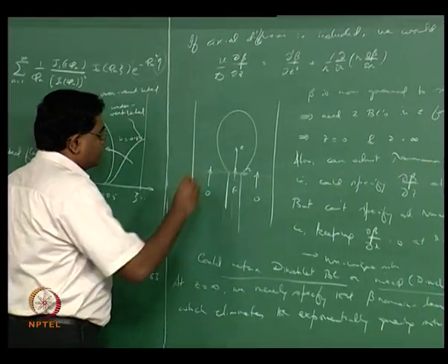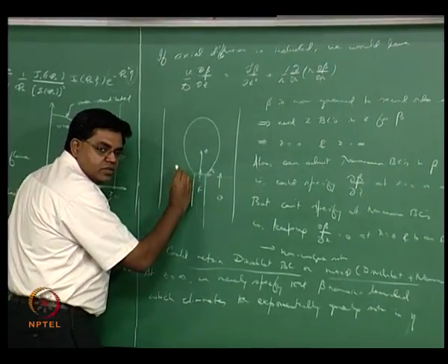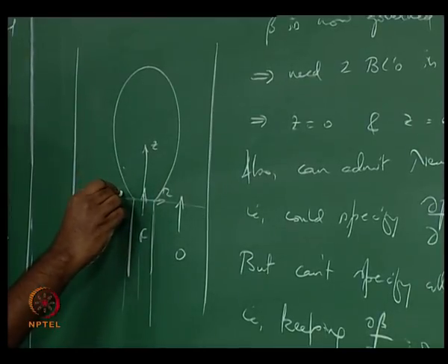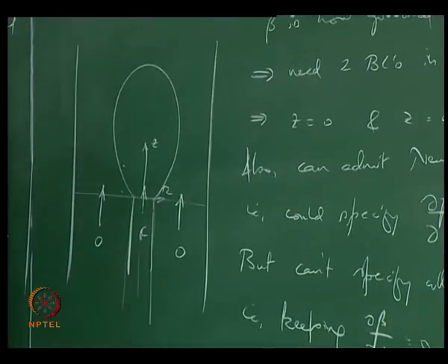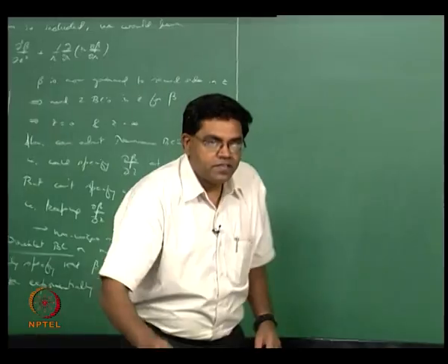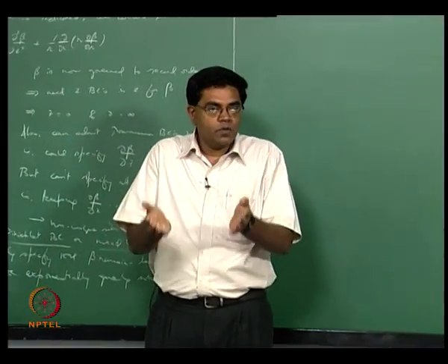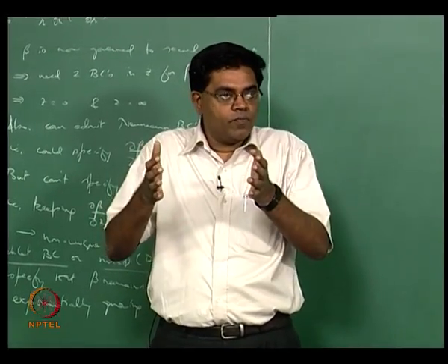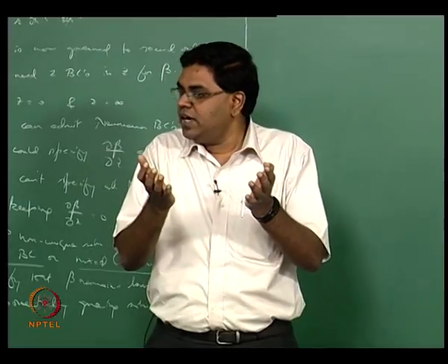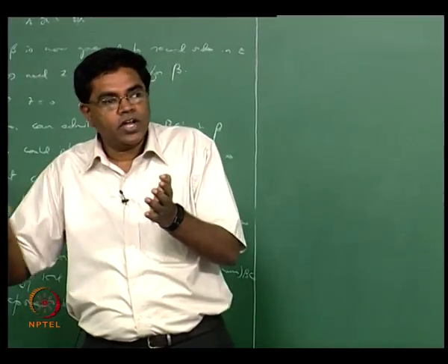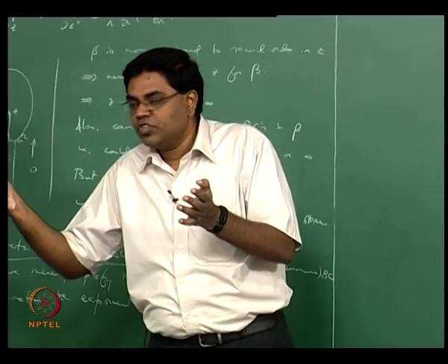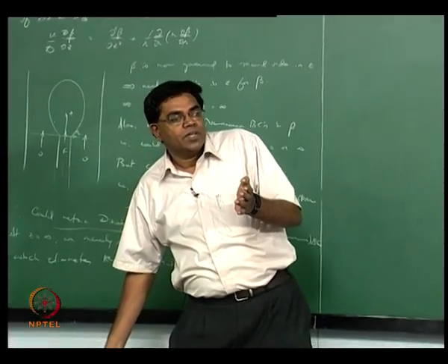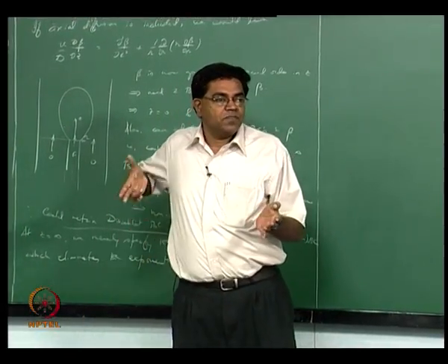What that means is, if you now look at it along the axial direction or the streamwise direction, you have more fuel here than here, right. So it is sort of like as the fuel is coming out and flows up into the domain, and you don't have the tube anymore, it's now got into the domain, it looks around and then sees, wait a minute, I am not there, so let me go there, right. And then once it goes there, it says, hey, wait a minute, I am not there, let me go there. What is that? That's axial diffusion, okay.